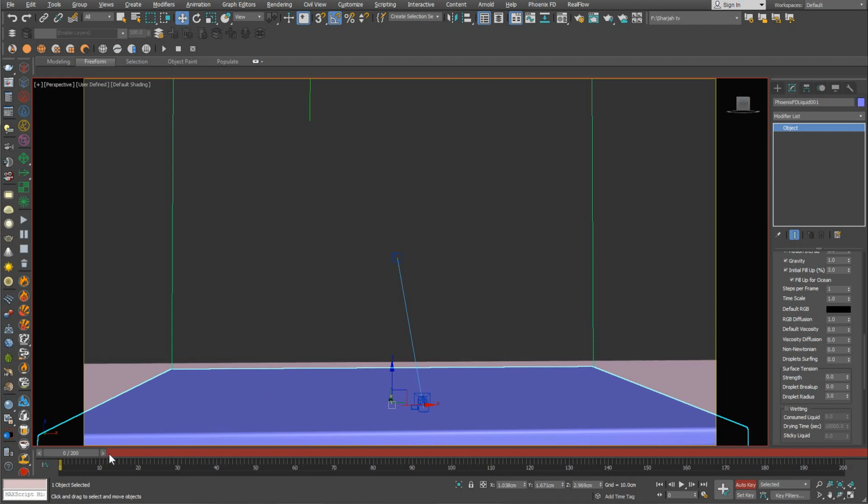So what I will do is go to the viscosity and start introducing just a little amount of viscosity. As an example, here in the beginning of time, I will say 0.005, which is a really small amount, but at least it will give it some kind of internal drag, as we call it. And for the surface tension, I can increase this to 0.1, as an example, and we can start the simulation again.